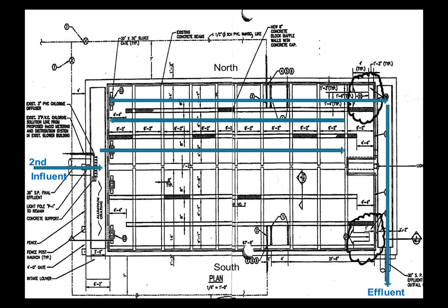So the kill is very effective. How it's applied is key, and again, knowing the hydraulics. We worked for 6 months to improve the hydraulics, make sure you put the right weirs in, the dams, the gates, and then we started the trial up again. So again, there's a mixture. 90% of it could be mechanical and 10% the PAA. But there is a balance between the two.